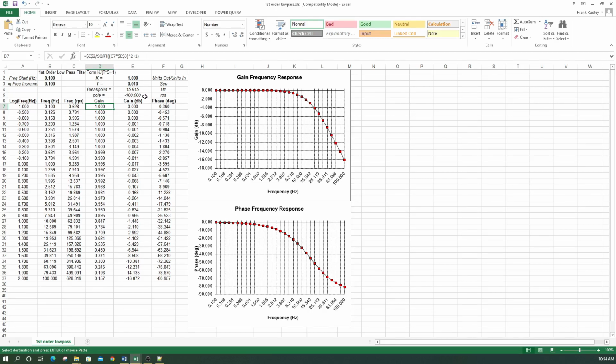You'll learn how to do this if you ever have a control systems class. To get the phase, it's the arctan 2 of, I believe, the imaginary over the real parts. So you could put a little formula in here to get that. I don't want to go into details of that, but anyway, we need to get our gain and phase here to do our comparison.